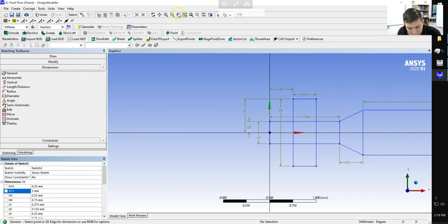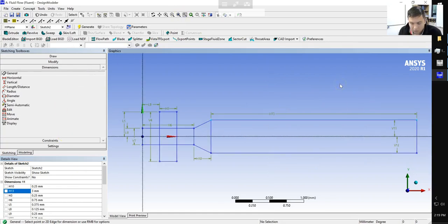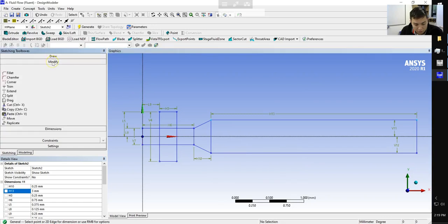Okay, so we can reposition, and this is our final geometry shape. Now, we've used the rectangles to simplify the drawing of this, but actually we have a number of extra lines that we don't need. In particular, these lines here, where we need to have fluid moving through those barriers, we need to go ahead and get rid of those. So we're going to use the modify function.